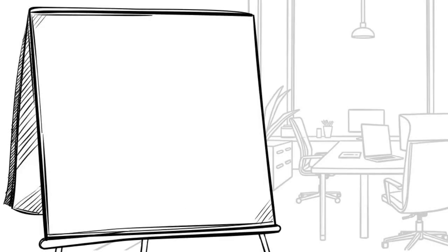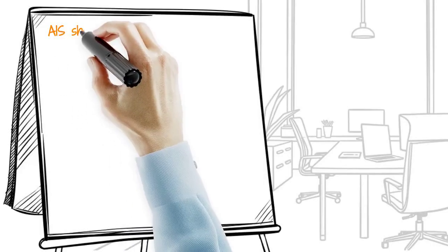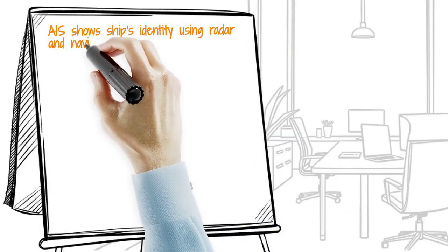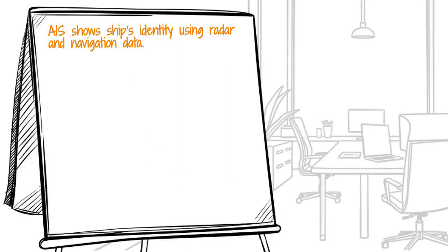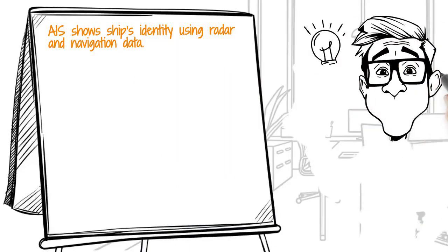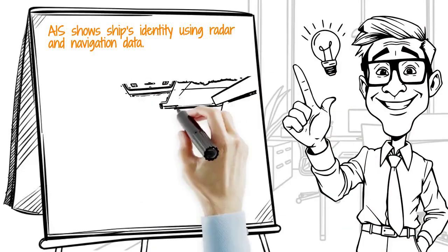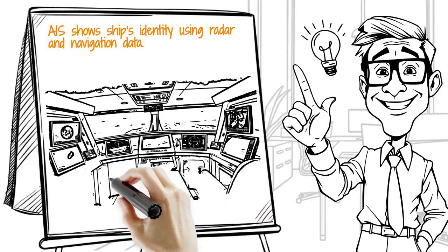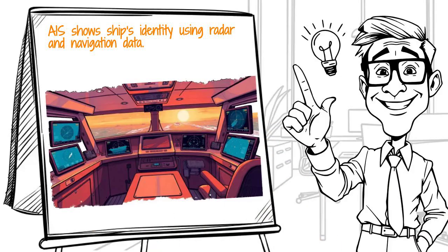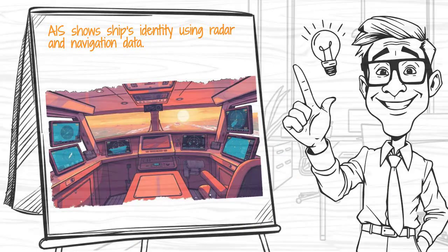Automatic Identification System, AIS, a novel radar-based system displaying ships' unique identification numbers alongside the radar vectors. AIS equipment consists of a central unit that collates information from the ship's navigation systems with pre-programmed information about the ship's identity and dimensions, and additional information such as voyage details.